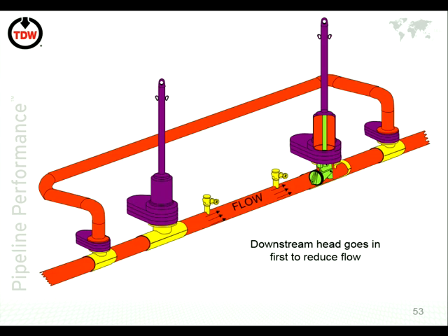Well, I imagine you tend to drop the pressure in the line when you are doing this. Sometimes they do, sometimes they don't have to. If the pressure is within the ranges of the stopple operation, then you don't have to stop the pressure. Similarly, if the flow through the pipeline is within the range of the stopple operation, you do not have to stop the flow.